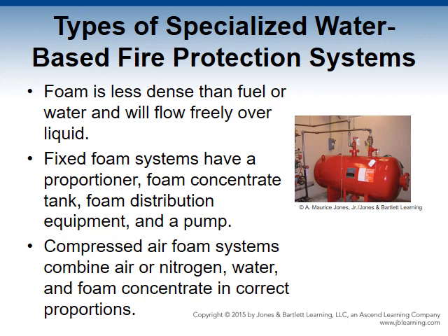Pumps. Installation requires pumps to move the foam concentrate or additives out of the tank, so pumps are necessary. It should be a positive displacement pump because it is better than a centrifugal pump when pumping foam solution.